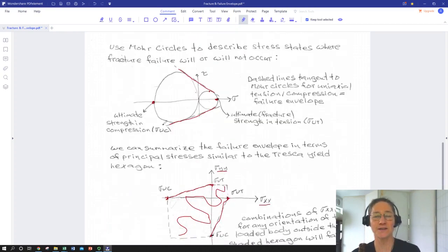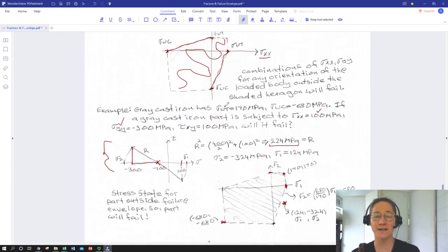We used just this construction that came out of a test to basically say we can take a complex loading that includes three different components and then relate that back to two data points from uniaxial tension and predict failure. This is not perfect, but it certainly allows us to leverage the data in our handbooks to great advantage.